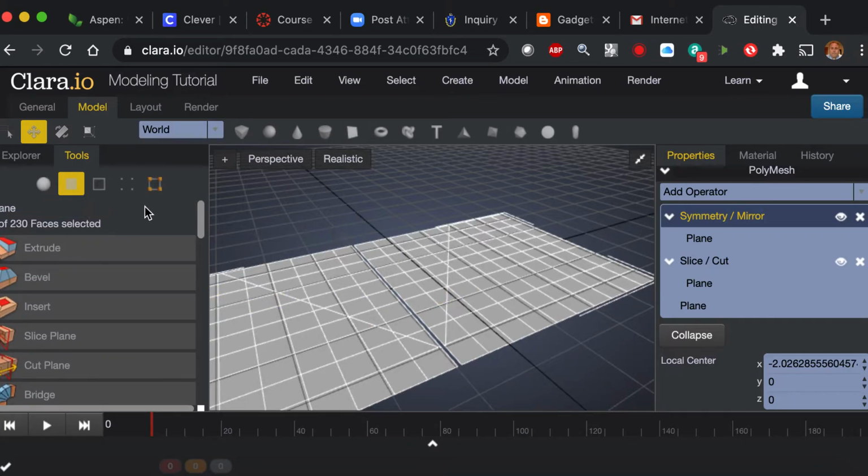So now when I do select faces, I hover my cursor or mouse over the surface, and whatever turns yellow, and again, I'm not clicking anything, you can absolutely select it. Or you can marquee select and select a range of components.